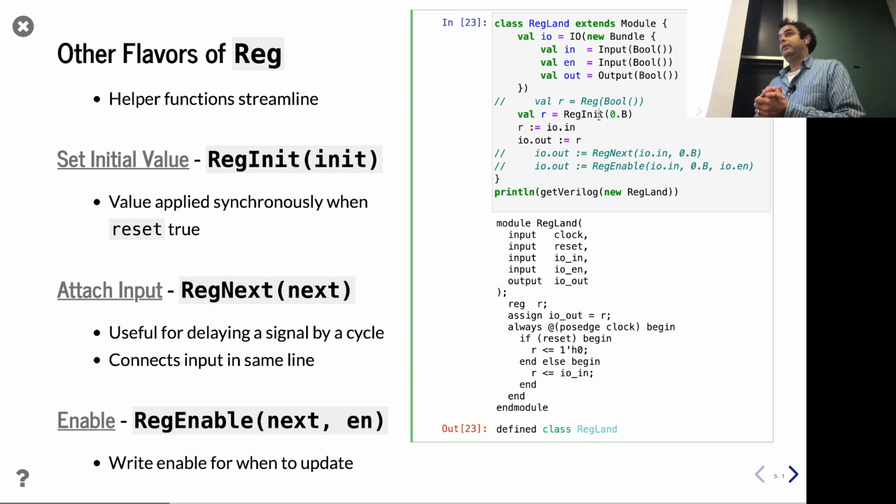And so this has been an escape hatch used in a handful of scenarios where sometimes in an industrial application, they have a certain macro they want to use, right? They don't want to just write Verilog. They want to have the exact Verilog snippet that their tool needs to do a certain thing. Like, you're writing on FPGA and they want to explicitly instantiate the FPGA's DSP hard block or something, right? In which case, you can use a black box where you put that Verilog inside a black box and you can instantiate that black box and get what you want.